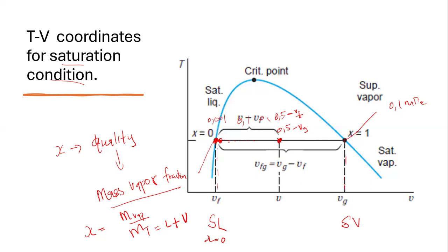And then F is for fluid, for liquid. So at this point in time, they are balanced. It's 0, 0.5, 0, 0.5. The more we move to the right, 0, 0.8, 0, until we get 1. So when we get to 1, here we have the saturated vapor.